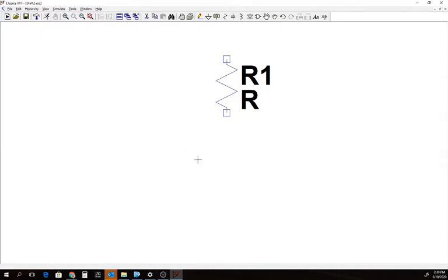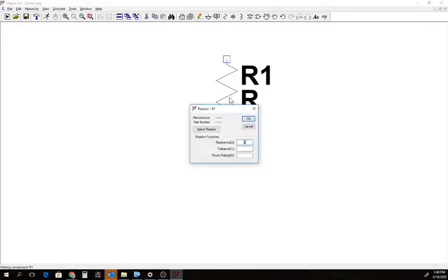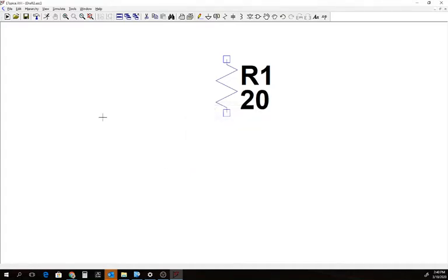The chopper circuit I'm designing, we're going to design this to handle only about 1 amp from a 20 volt DC source. So 1 amp from a 20 volt DC source means that my resistance should be 20 ohms, just V equals IR. So to put that component in there, up here you'll see there's a resistor.